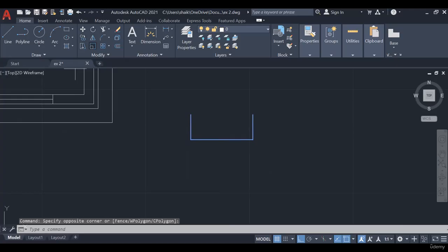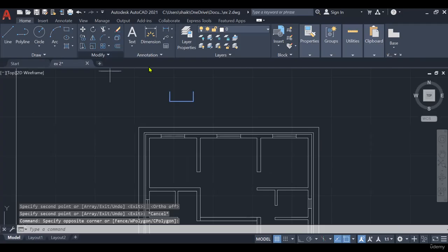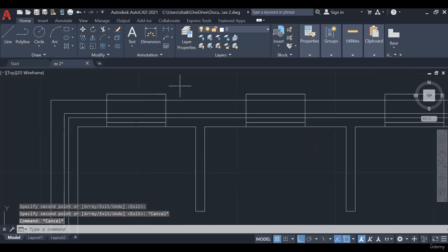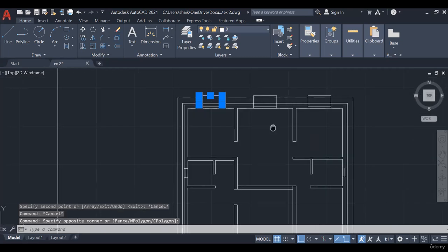But here we will not provide Chhajja because it is inside the veranda. So inside the veranda Chhajja will not be provided. Why are we providing the Chhajja? What is the purpose of providing the Chhajja? The purpose is to avoid dampness from rainwater on the window, and to provide a sunshade also. That is why they use the Chhajja.